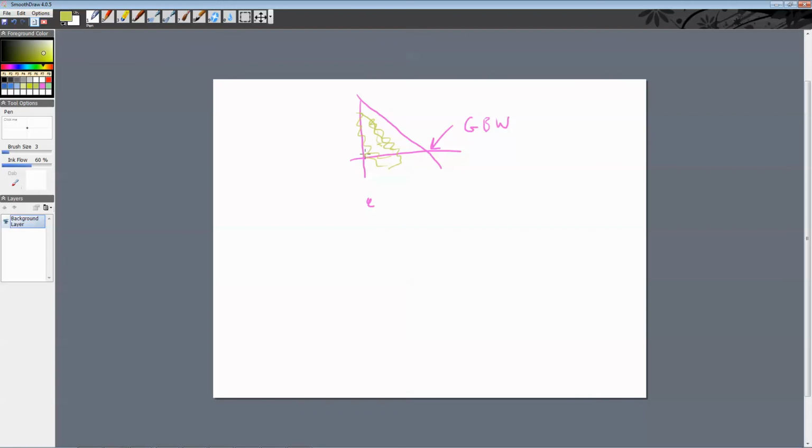Because in previous examples for looking at the gain of inverting and non-inverting, it comes out and then it gets limited. If I have a higher gain, it comes out and it gets limited. That's what we've done so far, and that's really with the 2 pi gain bandwidth divided by s model.